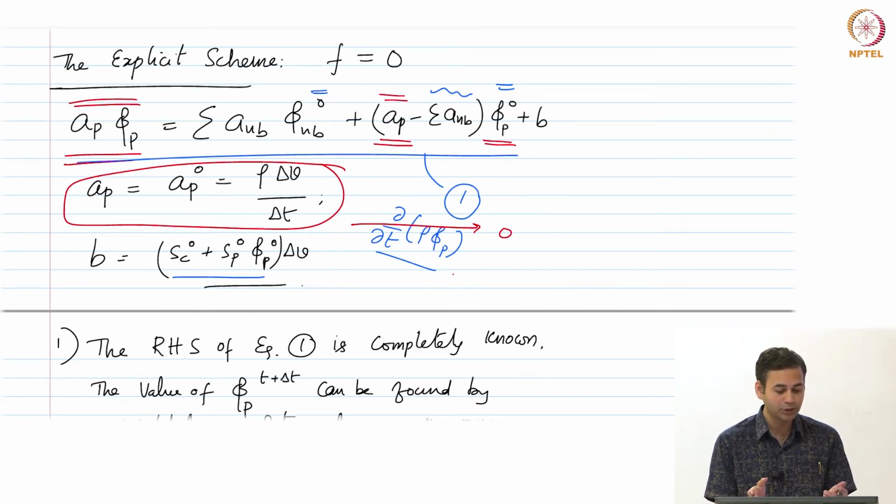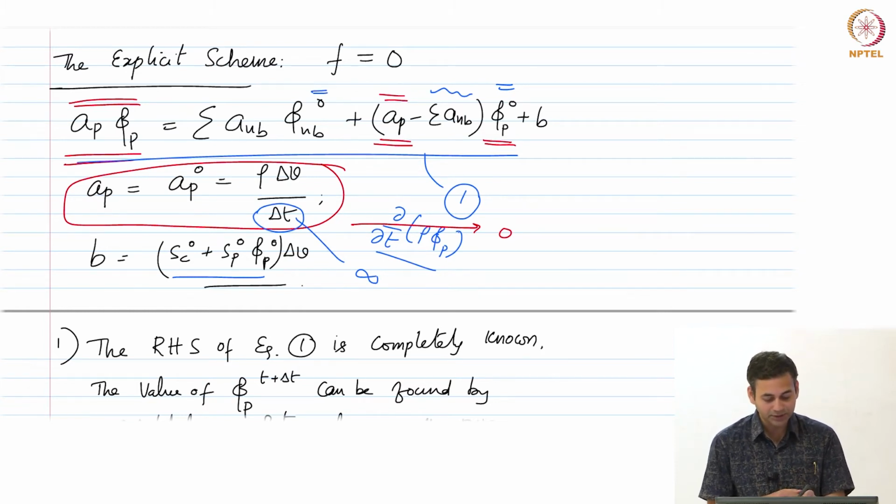Of course, another way to look at it is, in the context of steady state, your delta t kind of goes to infinity, right. You are looking at a steady state, so you are essentially independent of the delta t at a very long time. As a result, AP and AP 0 kind of go to 0, both of them, right. Delta t is time, so you should not look at it that way, but that is the only time scale you have. So, in the limit of a steady state, you do not have any time stepping coming into play, right. As a result, you do not have these coefficients AP and AP 0, which came about because of this unsteady term, that is partial t rho phi p, right, because if this goes to 0, then you do not have these terms coming into play at all, right. AP and AP 0 would not be there.